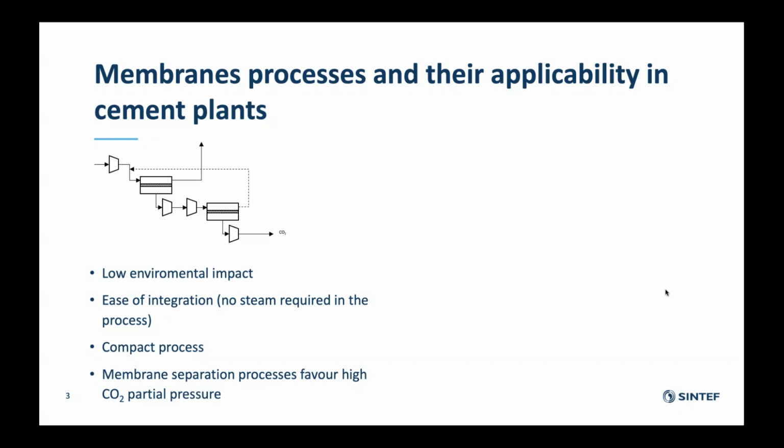And this is done basically to achieve the 95% purity, which is the specification of a two-stage process. Membranes are interesting from the fact that they have a very low environmental impact. It has a very high ease of integration here because the process doesn't require any steam, and also it's a very compact process. So from these perspectives, membranes are really interesting from an environmental perspective and a retrofitability perspective.